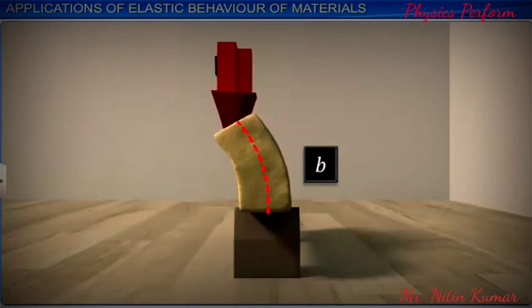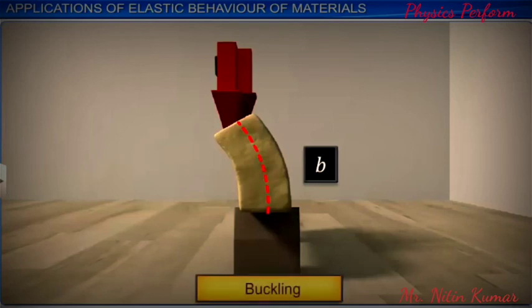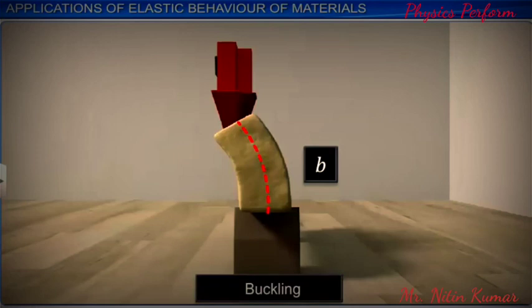Thus, the beam can buckle under asymmetric loading, which is the case in bridges that carry differently distributed traffic at different times. To avoid this, the cross-section of the beam is chosen to be I-shaped, as shown.